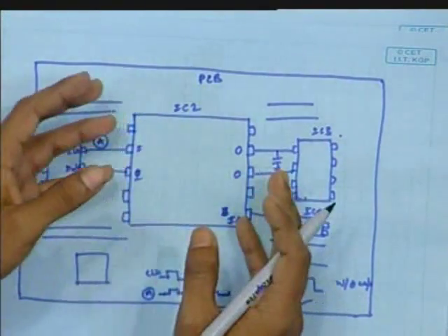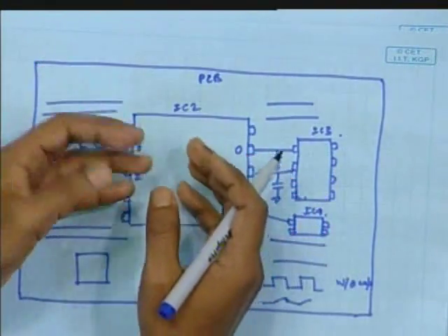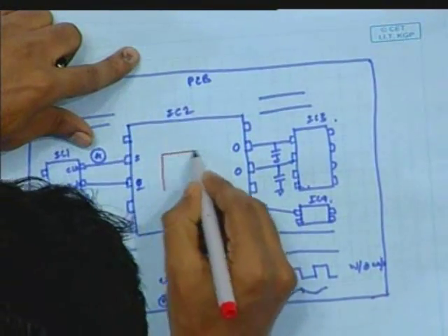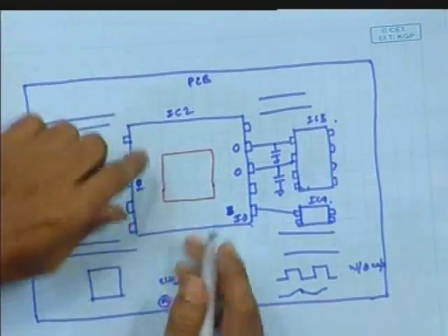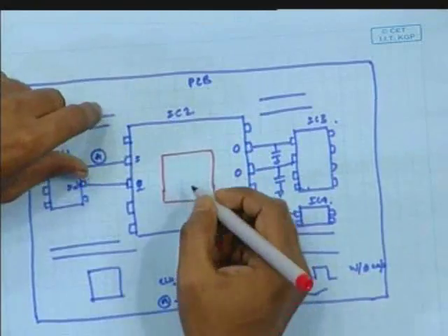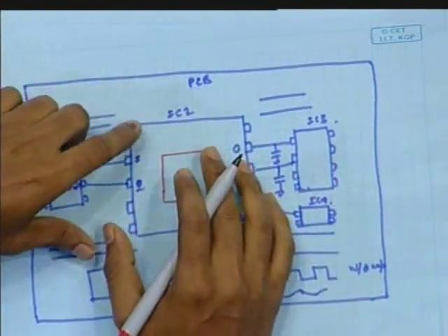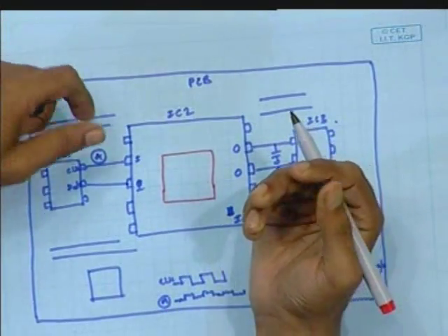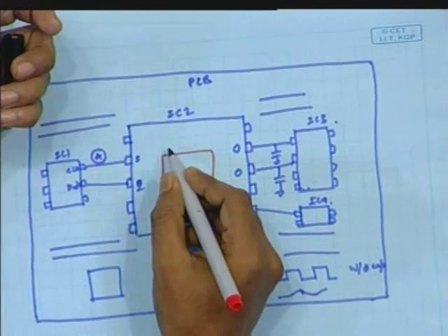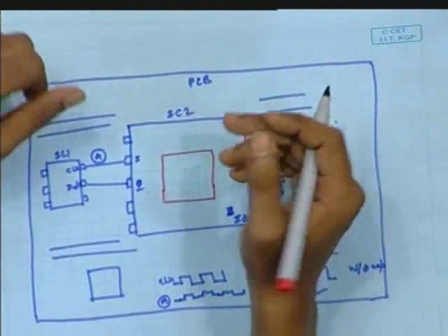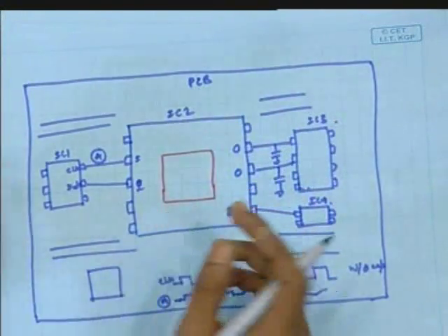To get the speed we are planning to use a lower gate length for the core transistor. So consider this is the core transistor, this is the core portion, the main processing portion, right? Speed is mainly determined by this portion, right? So we want to process everything very fast, so we are planning to use lower technology, consider 0.35 micrometer technology. For 0.35 micrometer technology, what can we use? We can use here a maximum of 3.5 volt. We can't go more than 3.5 or 3.6 or more than 4 volt, because if we use more than 4 volt, the oxide will be stressed, right.